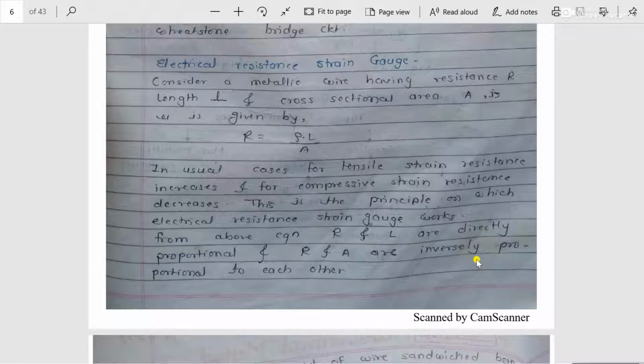because the resistance of the strain gauge will change if it comes in contact with any loading condition or any moving component. So what is the first requirement? If I have to use strain gauges for any application, before that I have to paste or bond that strain gauge on the specimen. And if that specimen comes in contact with loading, or is in a moving condition, then due to that, its resistance will change.